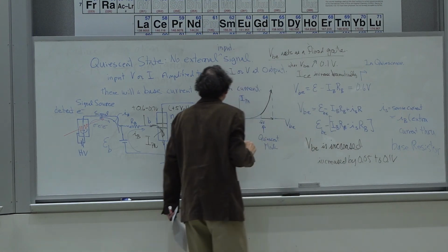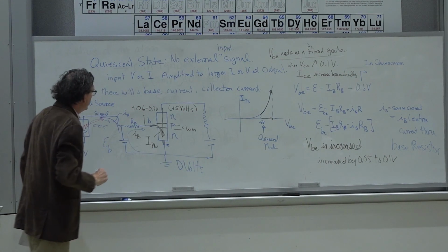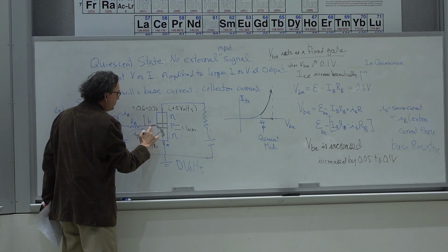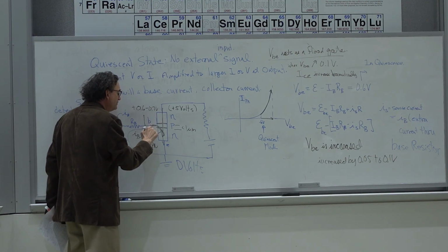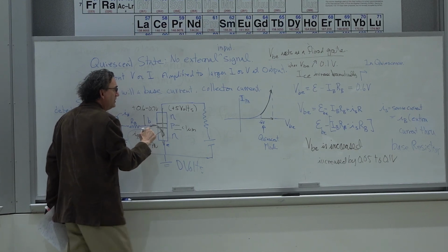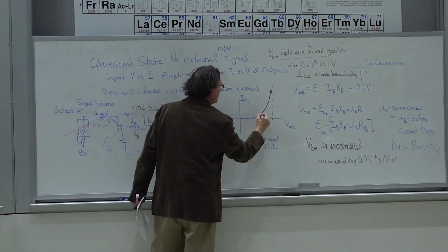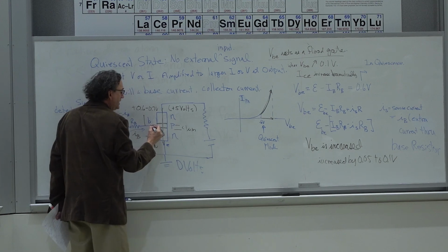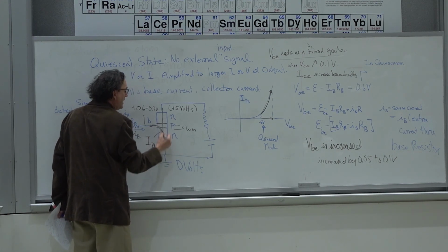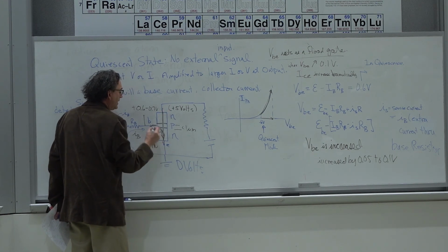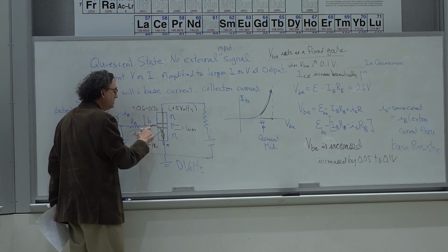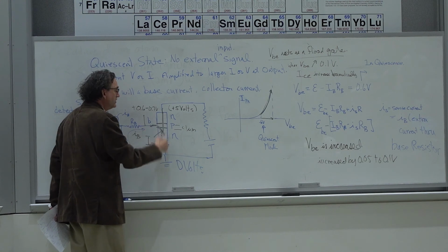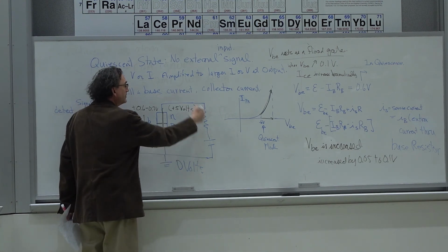Okay? So the idea is that once this point, I'm going to keep saying it again and again because it's a very, very important point. When this voltage changes from 0.6 to 0.7, the current begins to rush across here and also through this way. In other words, this acts as a gate. It's a floodgate. When it's below 0.6, there's very little current and very little current coming through this link.